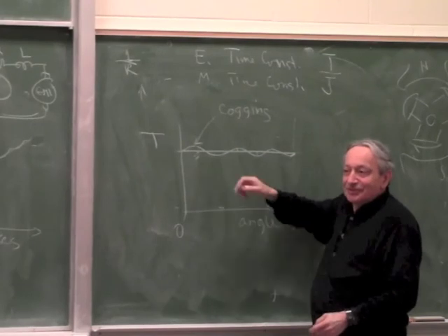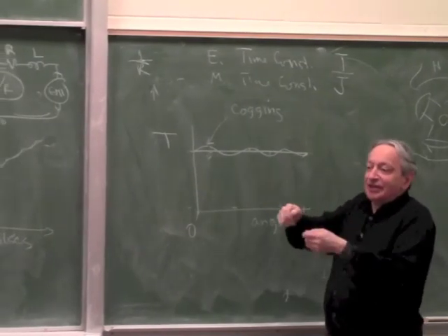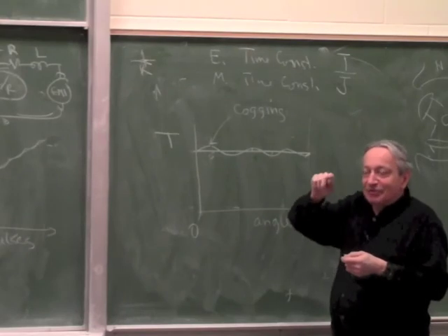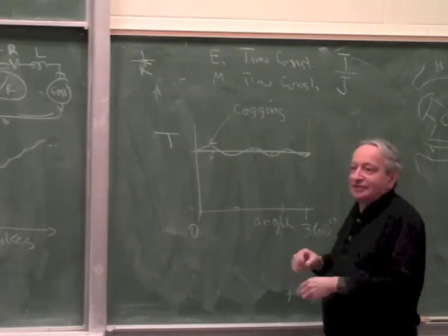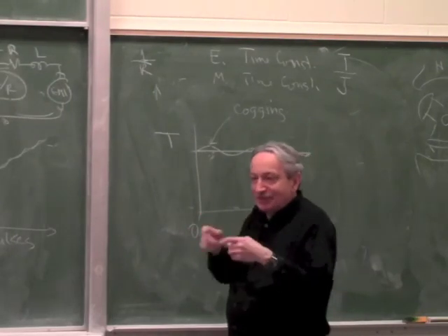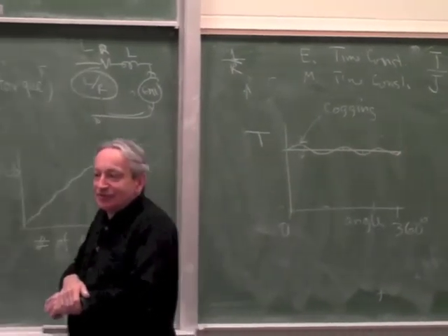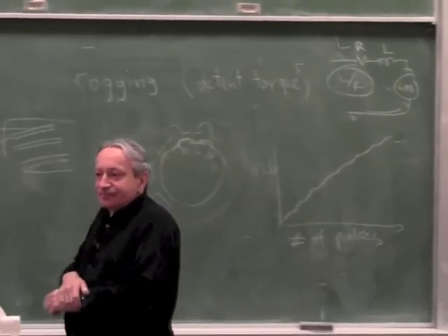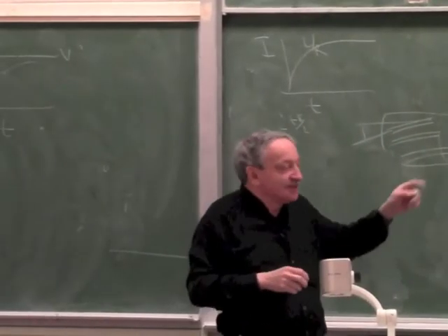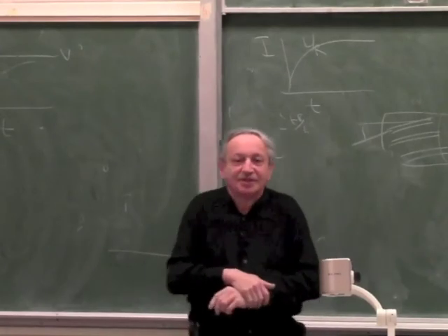So when you say you have a rubber band attached to the motor trying to wind it up, the speed will fluctuate a bit like this graph. And this happens at a high rate. It's sometimes difficult for the servo to remove that. Say if a motor has many poles, this is quite a high frequency disturbance.